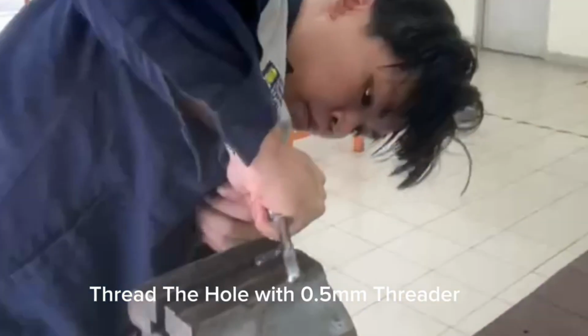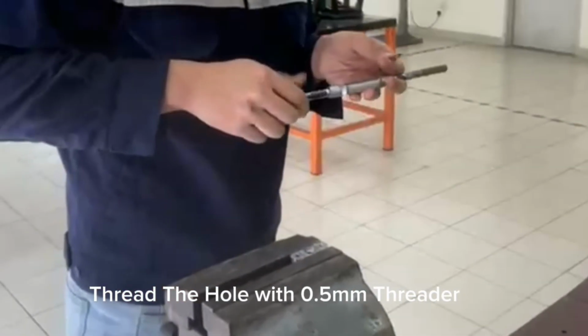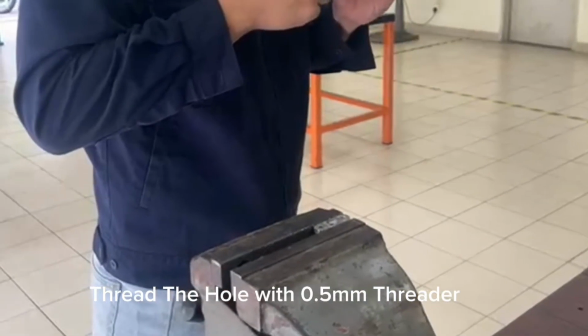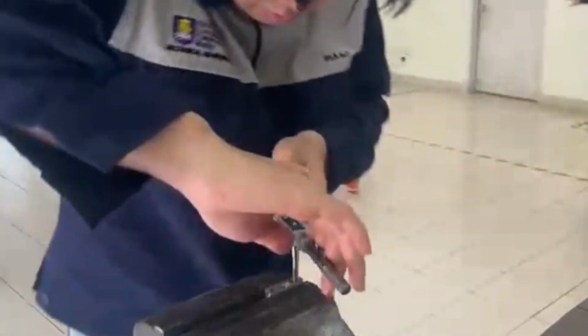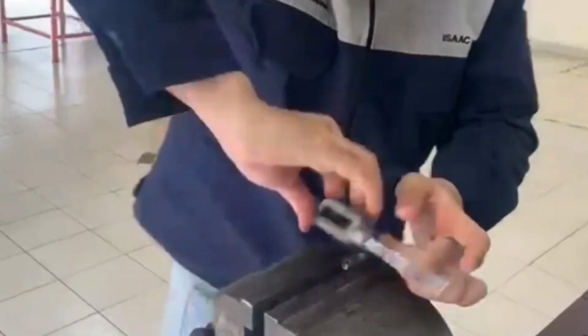Lastly, the hole was threaded using an M5 x 0.5 tap. There's a problem here: the tap was turned too fast, causing excessive friction, and the result was poor thread quality. For the solution, we threaded it again, and it happened to be good.